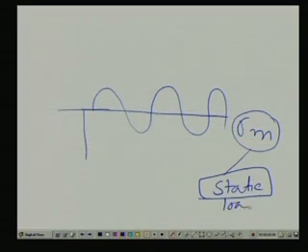So, this is a static load, over which you are superimposing the fluctuating stresses, the repeated stresses, or the complete reversal stresses. That means it is a mean stress over which sigma a, the stress fluctuation, is being superimposed. That is the basic idea of the design.